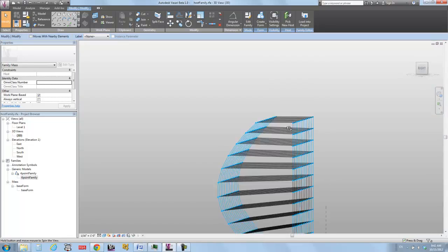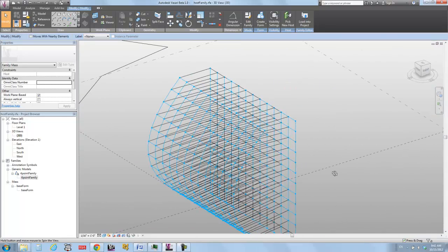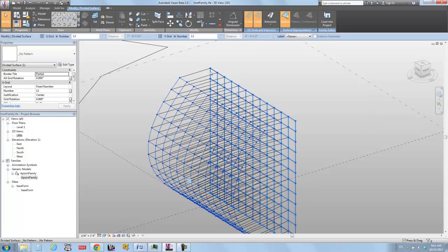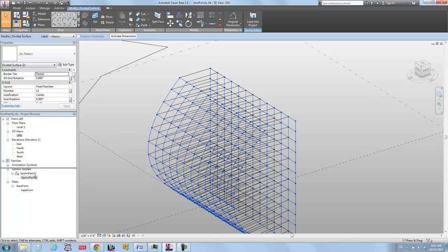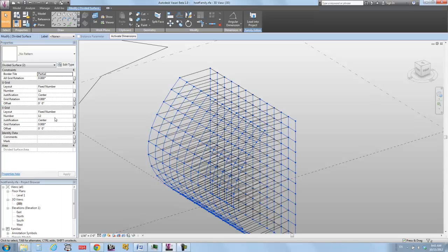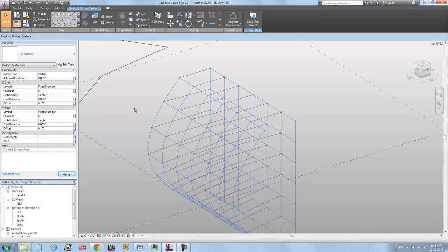And you can take a look at it here on the side. If you tab select to the divided surface over here and then hold control, basically what I'm doing is selecting both divided surfaces. This is a fully parametric relationship still, so you can go change the divided surface to be a different resolution. Go ahead and let's change that to 6 and just see how it simplifies the relationship down. You can increase and decrease the resolution.